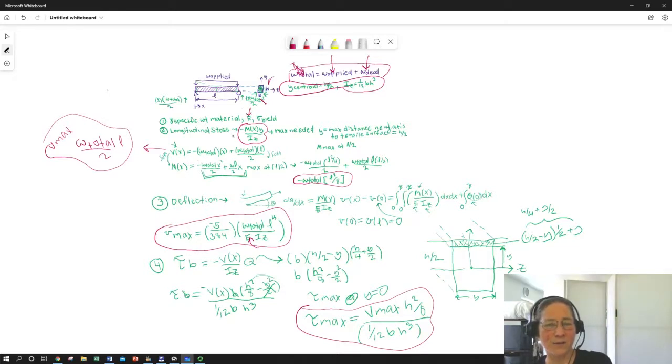I would look up my modulus for my material. I would decide how long I want to make the beam. Pretty much everything else will flow from that. Then every other characteristic of my material tells me whether I have exceeded it or not.